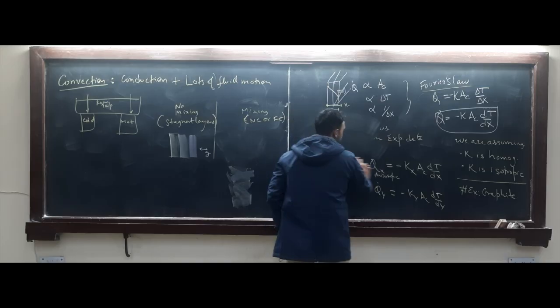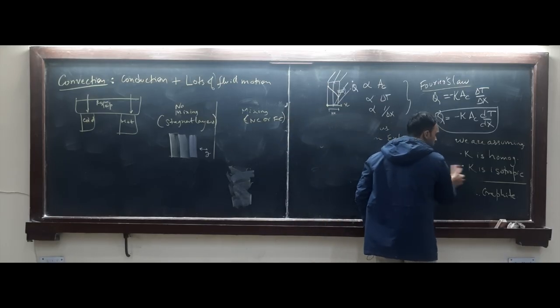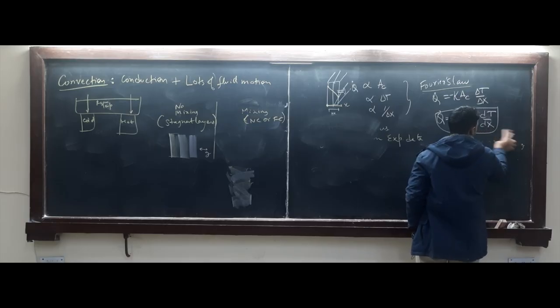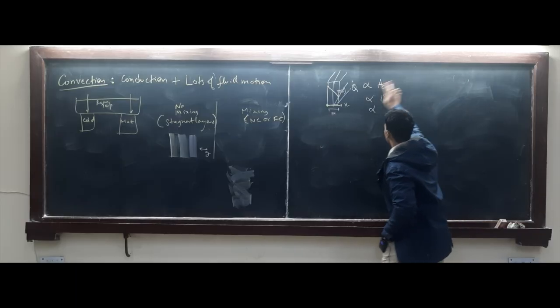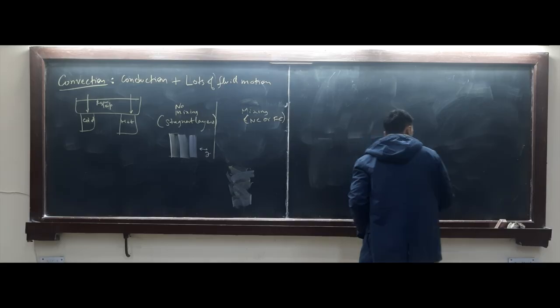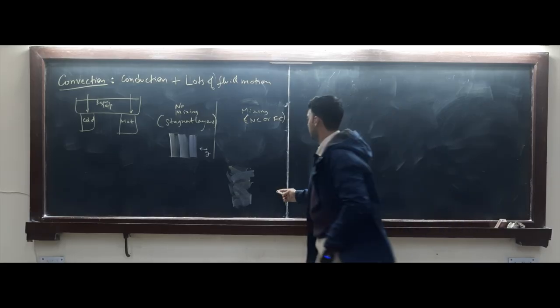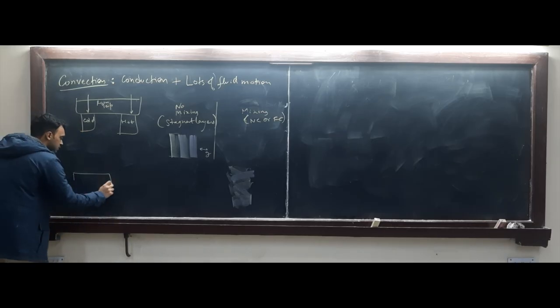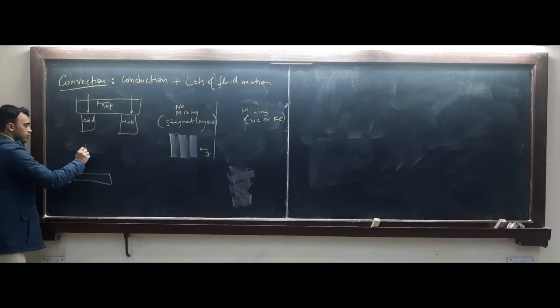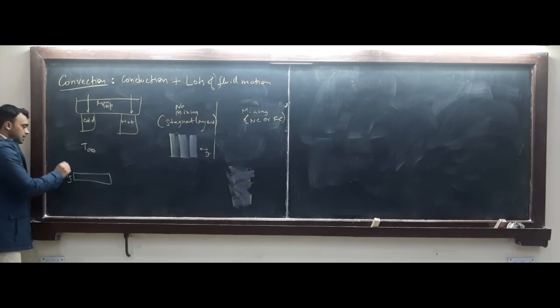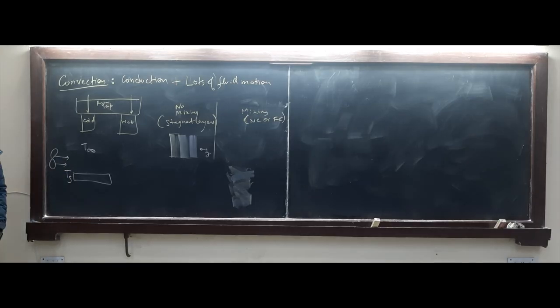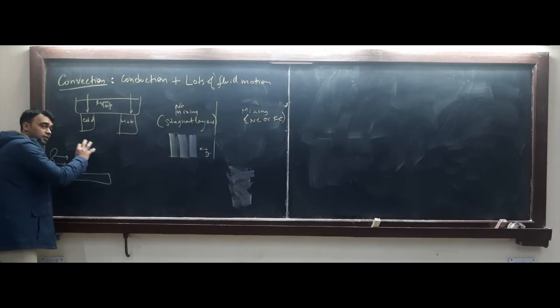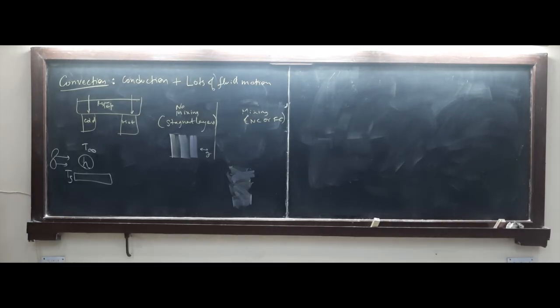Now that makes us think that fluid properties must play a major role in determining the heat transfer coefficient, right? So all this is lumped inside heat transfer coefficients. If you forget about forced convection, natural convection for now, if you have a hot surface at Ts, if you have ambient temperature as T infinity, and you switch on a fan or natural convection is going on or a mixture going on, the property that defines this convection, as we saw in the first class, is the heat transfer coefficient. Yes?